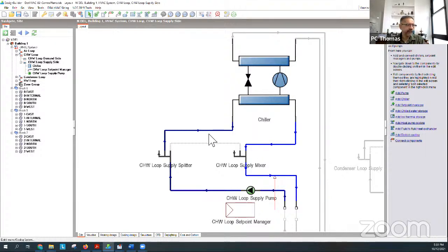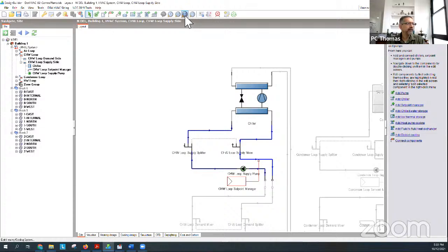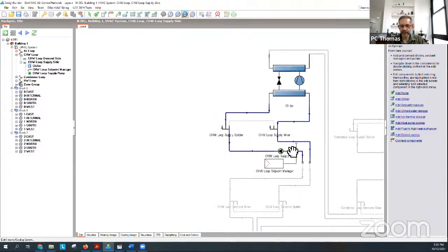Okay, but really when you have two chillers in a plant room, each chiller has got its own pump. For safety's sake, most engineers like that, so that when a chiller starts, its pump comes on first, maintains flow, then the compressor starts. So there's no chance of the compressor burning out. Okay. A lot of engineering here, I apologize, but it's good if you know that. So now what I'm going to do is I'm going to select that chiller.